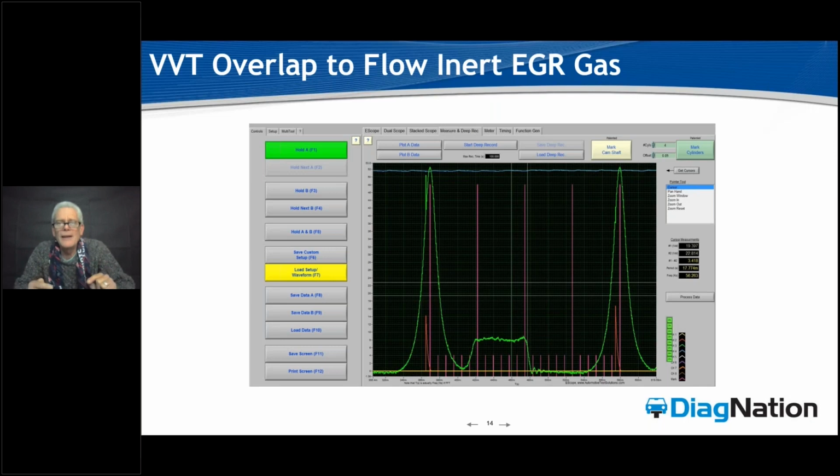And gas direct injection cannot work properly or burn properly, cannot, with a capital C, with carbon fouling over that valve, because the minute you interrupt the tumble, you now interrupt how that tumble is controlling the rich ball of fuel in the lean cycle that's supposed to be held right up by the spark plugs so that the cylinder lights evenly. The second we get that carbon buildup around the valve, all bets are off there.